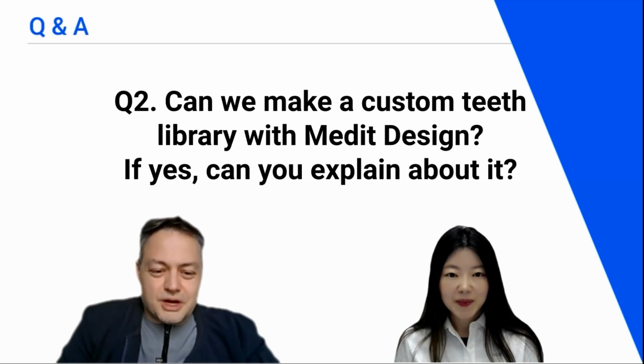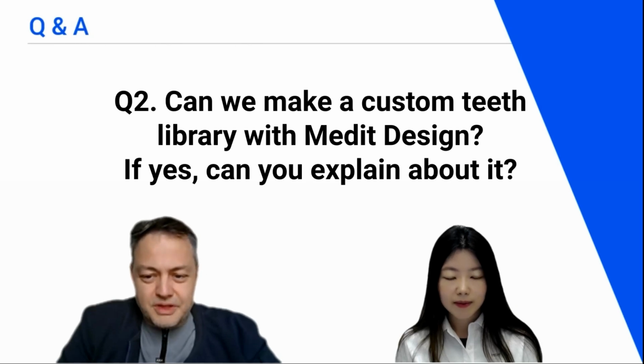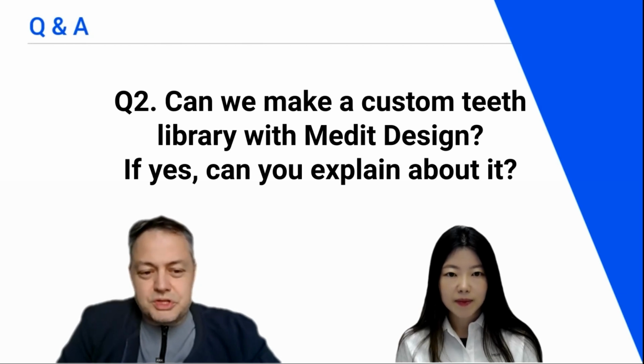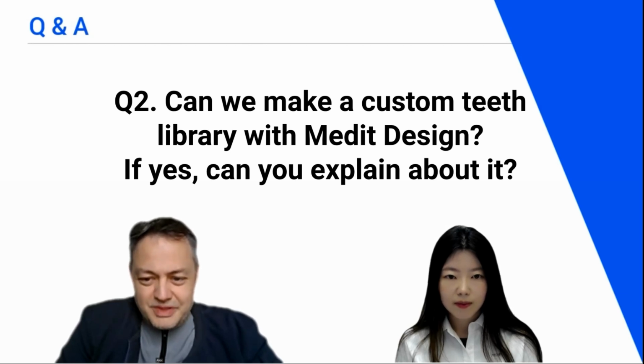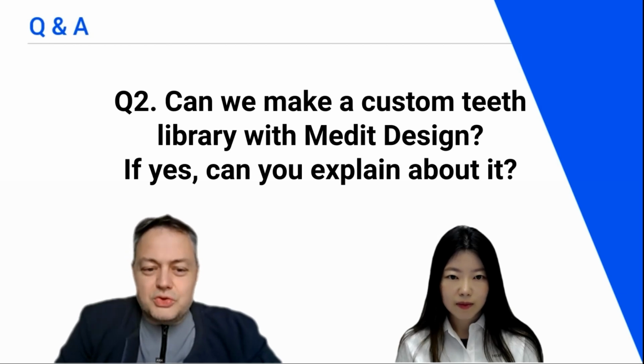Yeah, so my workflow here is to actually go to ExoCAD and plan a full arch of teeth, and I'm using their full anatomic libraries, any library I need, and I just put it outside the arch. Then I export every tooth from the library and bring it in Medit Design. Medit Design offers a custom base, and you place the custom base in contact with those teeth that you just imported. You Boolean merge it together,